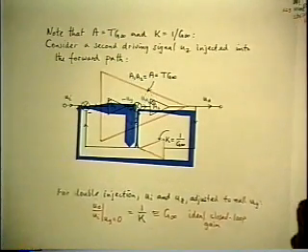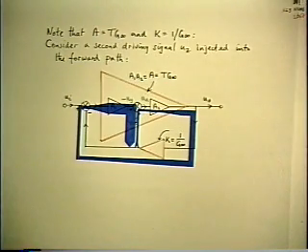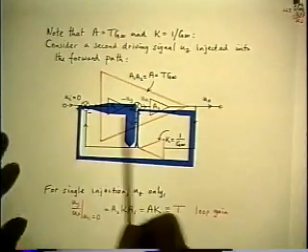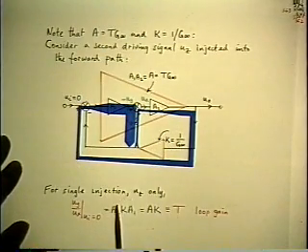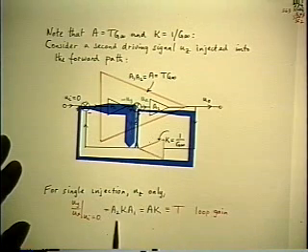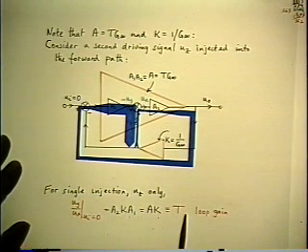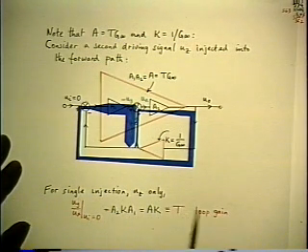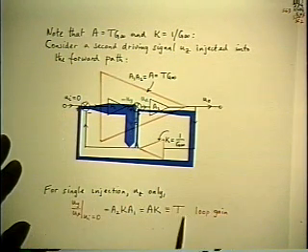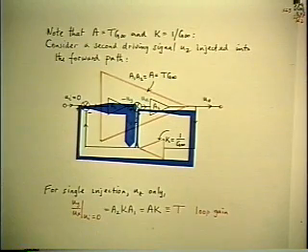So in this case, it's the wrong picture. In this case, the UI is 0, and you follow the signal from UX back to UY, and you go through the full loop gain to do that. So that's how you calculate loop gain. UY over UX when UI is 0 is T. That much we've done already also.